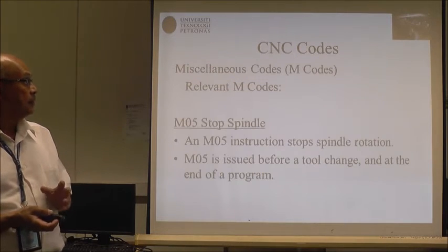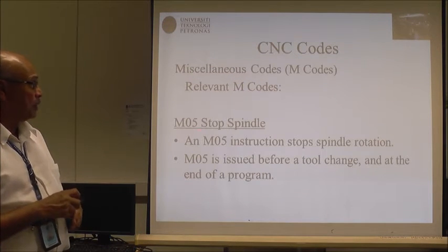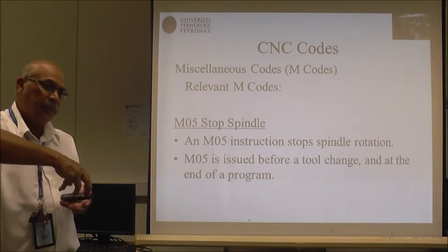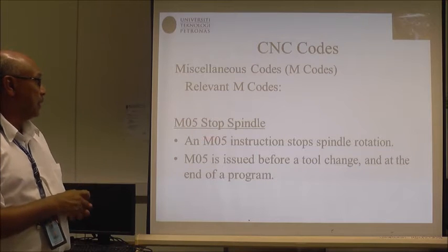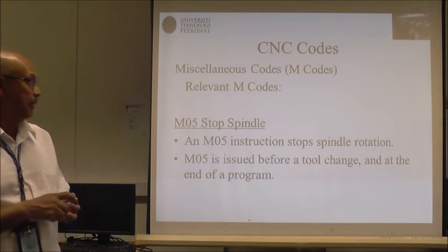Okay, next. If you want the spindle to stop, for example, you have done the cutting, you have returned the tool, you want it to stop. So you give an M05 and the spindle will stop. Okay, next.